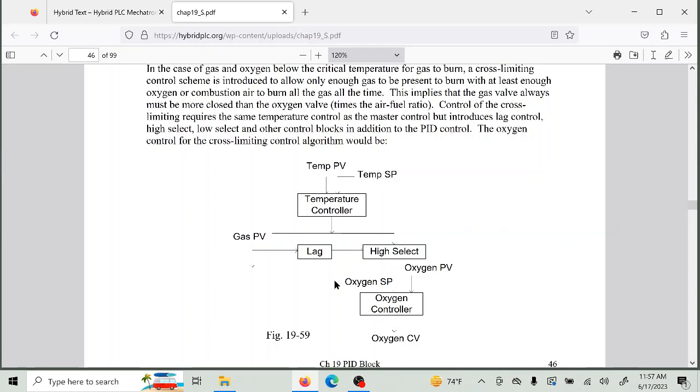However, if you get to 9.0 or 8.9 or 8.8, what happens? Well, the excess gas pools. If you're at 2100 degrees Fahrenheit, that excess gas burns off. It just goes up the chimney. But if you are at 8.9 or 9.0 and you're in a steel furnace and you're running at less than the temperature at which natural gas burns off, your natural gas pools.